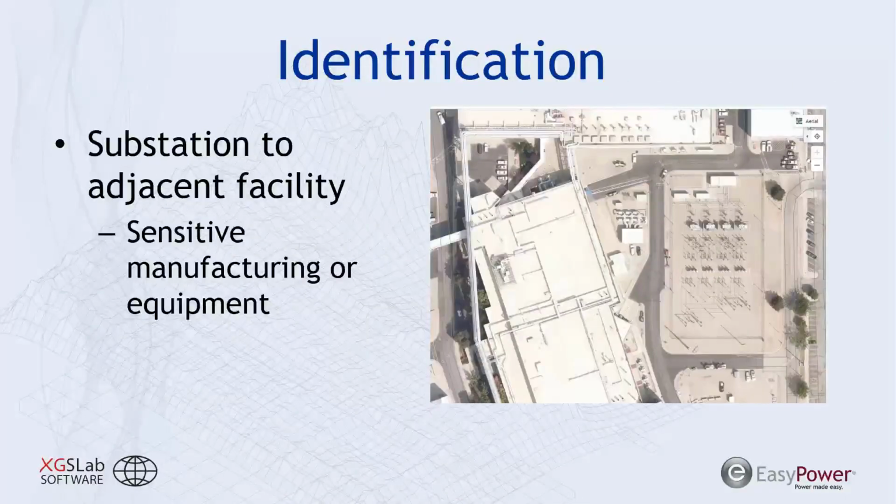Finally, I just wanted to mention another type of recipient we could look at, and this is really a facility. It's important to note that in some manufacturing facilities, there can be equipment that's very sensitive to ground potential rise. And in an instant during the manufacturing process, if that's interrupted, that could cost them hundreds of thousands or millions of dollars in the instant that a fault occurs if we're not being cognizant of that sensitive equipment for our ground potential rise and transfer voltage issues.